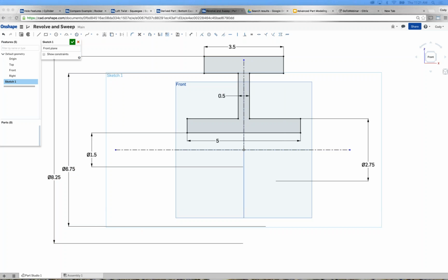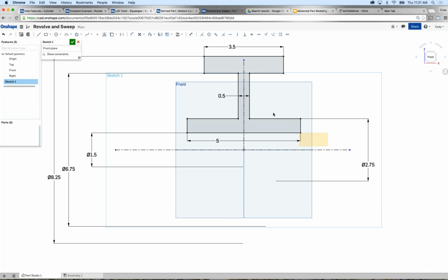Another question. Can you do a left-click crossing and select all three lines without having to individually select them? Absolutely. You can window select, what's often referred to as a window select, where you just simply left-click and drag a window. Okay? Anything in that window will be highlighted.